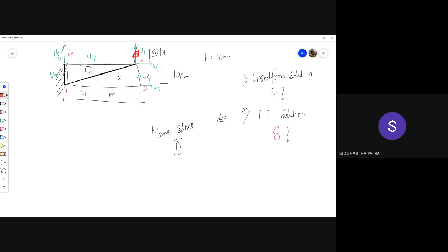So the point loads are going to be like this. The force vector, the one coming from the external force, and the reaction force. The reaction force is going to be R1, R2, then 0, 0, 0, 0, R7 and R8, and the force vector is going to be 0, 0, 0, 0, 0, 100, 0, 0. Those are the only two contributors to the force vector.